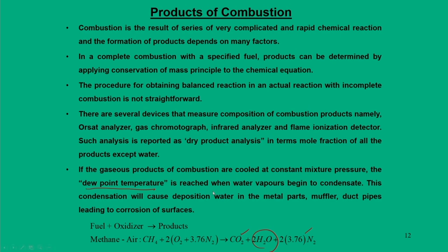Okay. The very basic point is that when the vapors begin to condense or liquid droplets are formed, they effectively create corrosion in the metal parts, duct pipes, all these things. So, this is the downside of the combustion process, that continuous exposure of the metallic parts to water leads to corrosion and further damaging of the surface.